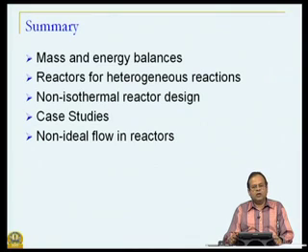And for the stirred tank reactor, we wrote a general mass balance, so that we can emulate a batch process, continuous process or a semi batch process using the same set of mass and energy balances, only appropriately changing the feed rates, where for a batch reactor there is no feed in and out, for semi batch there is only feed in but no feed out, and for a continuous reactor there are both feed in as well as feed out.